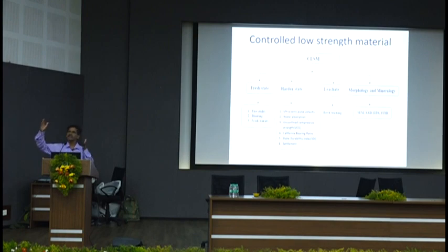Today, during infrastructure development, you see they make a trench, put the pipeline, then put the sand in it. After one rainfall, you will see there is a depression. Then they put some concrete also, which gets cracked and depressed. So these are the places where they first tried to use this flowable concrete, instead of, I will say, controlled low strength material. The name should be exactly, we should honor it, that is CLSM. It is just similar to your self-compacting or flowable concrete. There is no need of compaction, no vibration.